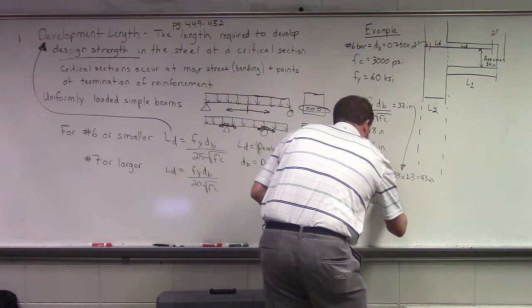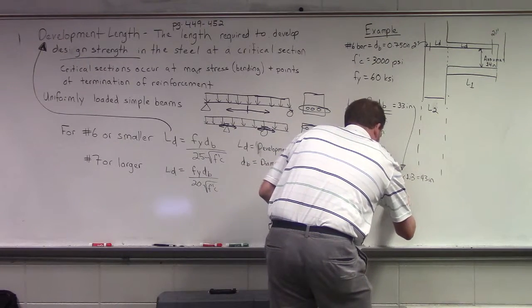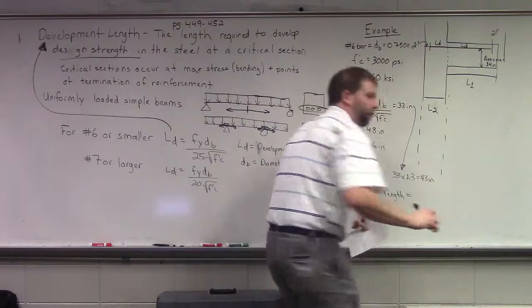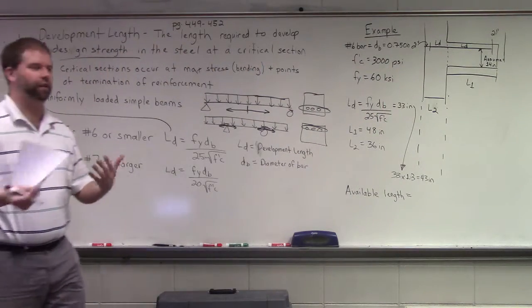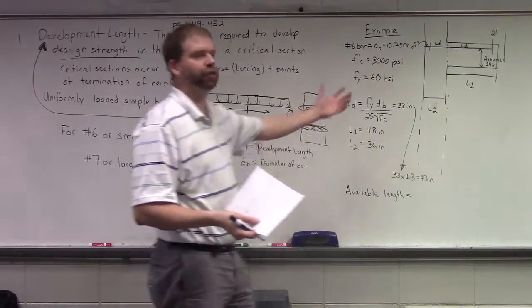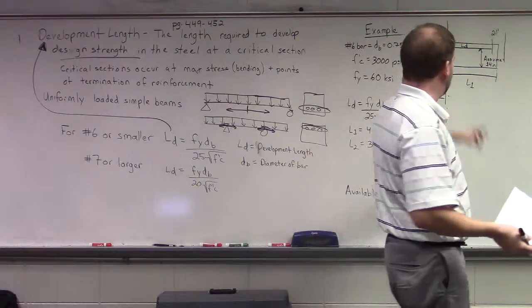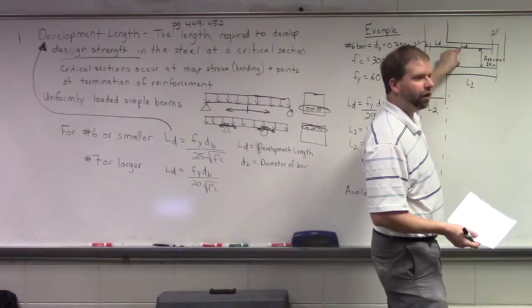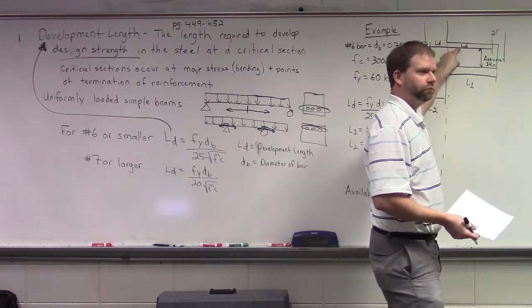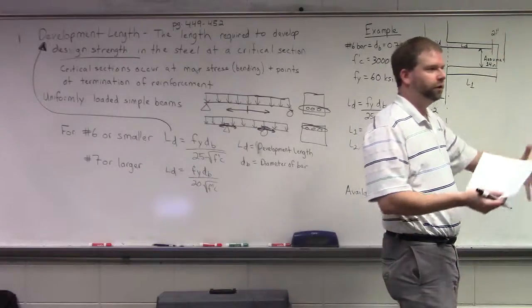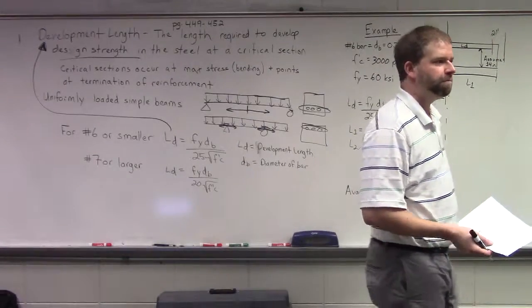Do I want to ask the question where you got 1.3 from? No. It's a given number that lots of engineers got together and figured out as a consensus. That's what they need to use. It's a constant value. Anytime this dimension is greater than 12 inches or greater, you just multiply it by 1.3. Okay? It's not a scaling factor. We're assuming it's 14. Yep.